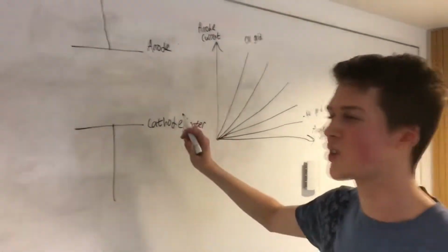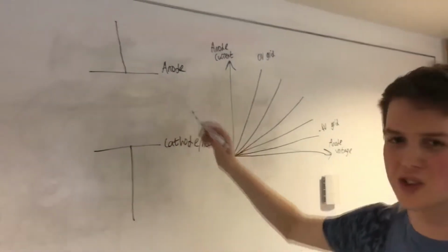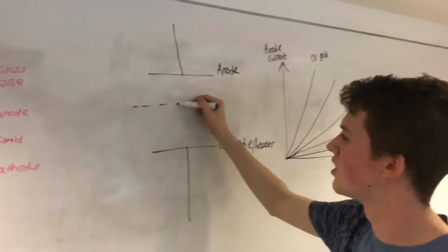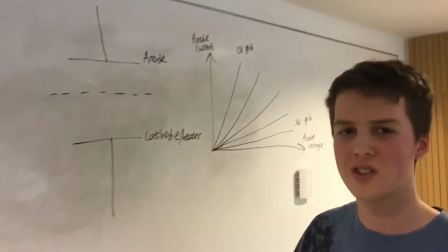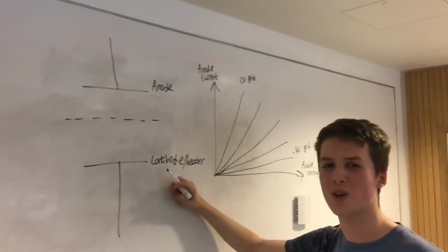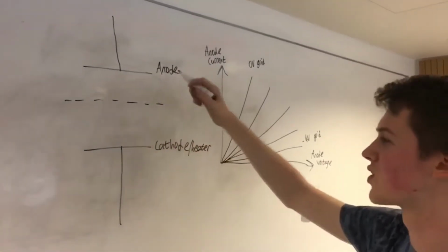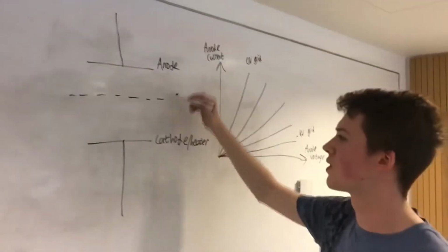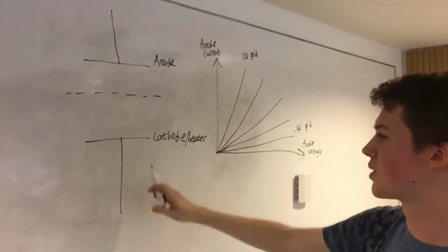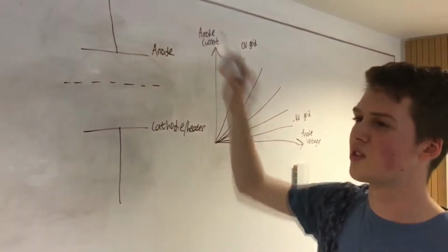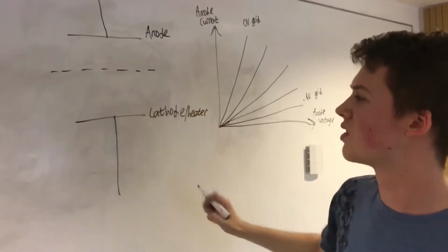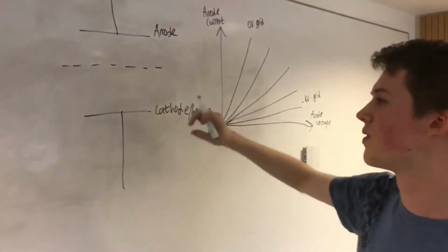So, from our diagram of the diode with the two electrodes, we can simply convert this into a triode by adding a control grid, which is a metal grid with a potential difference across it, which will affect the thermionic current between our two electrodes. With a positive potential difference on this grid, it will accelerate the electrons emitted from the cathode towards the anode, which will in effect amplify the original current that would have flowed through the diode.